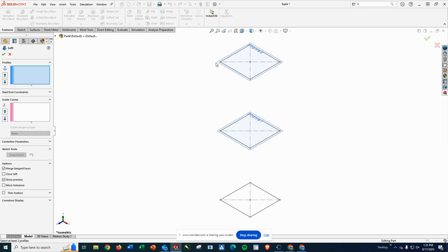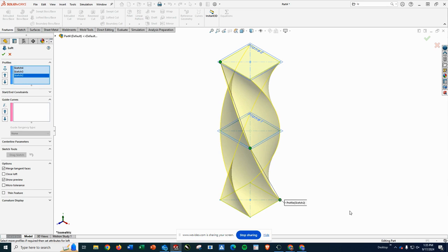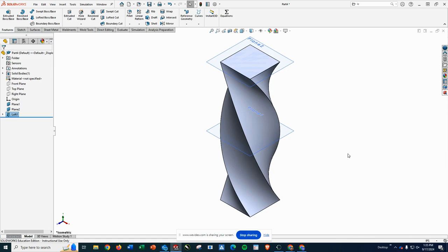All right, so for whatever reason, it kicked that out. So let's try again. So we'll go here and here. And then to go down to the next one, that's where I'm going to pick the one opposite where I started, so it continues to twist, and it goes there. So by using those curves, I can actually twist my piece. There's actually in SolidWorks no other way to do this. So I'm going to go ahead and accept it. And this is my twisted piece here.